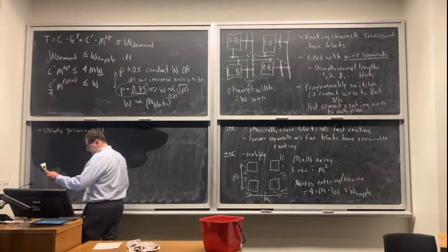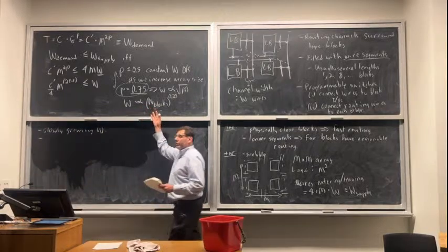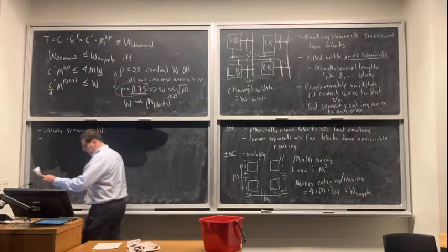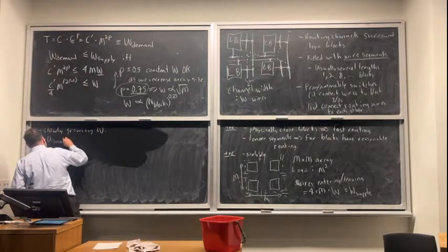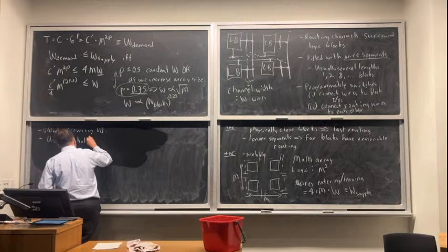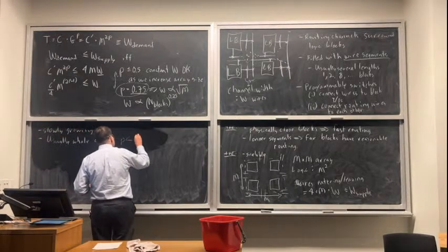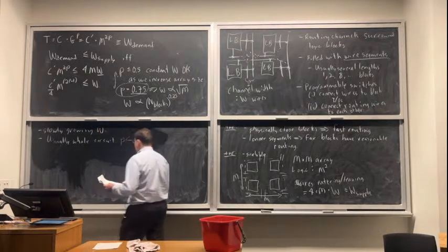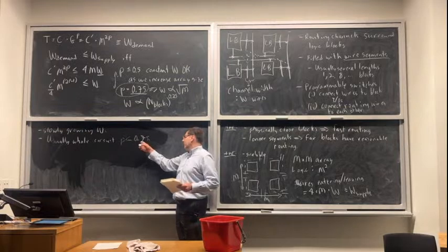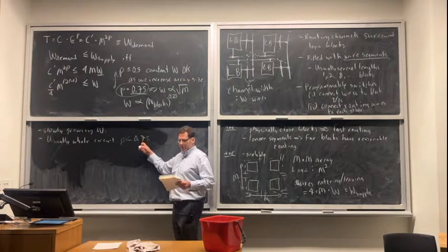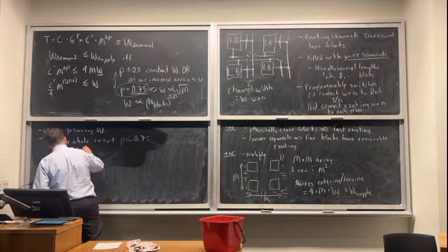Now with capacity, in practice the whole circuit's not usually 0.75. There are cases where it is, but they're not common. So you can grow W even less than that. You do definitely get random logic pieces of a circuit that have a Rent exponent of 0.75, but your CAD tools can usually just space those out.